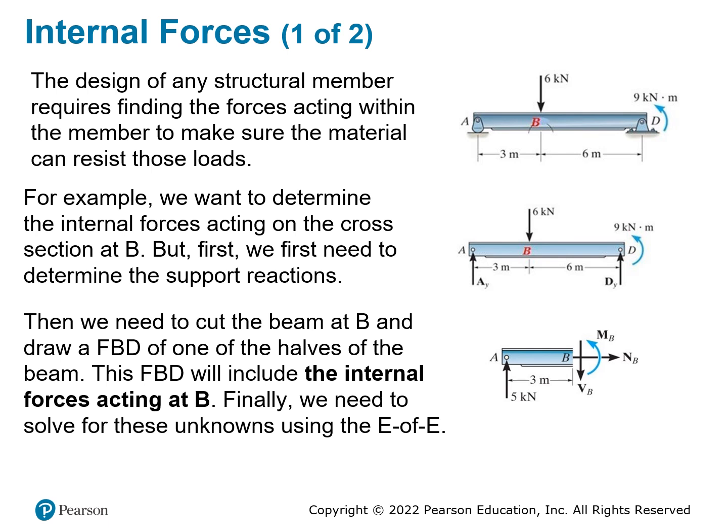Before we start the analysis, let's understand some of the terminology. What are the internal forces? When you see a structure like this, we apply a 6,000 Newton force at point B, and at the end, which is point D, we also have what is called a moment, right? By looking at the unit up here, you see there is a moment here. But what we want to understand is whether each part of the structure is going to have the same amount of loading or not. Meaning internally, do they have the same amount of force and moment? And the answer is going to be no. How do we analyze this?